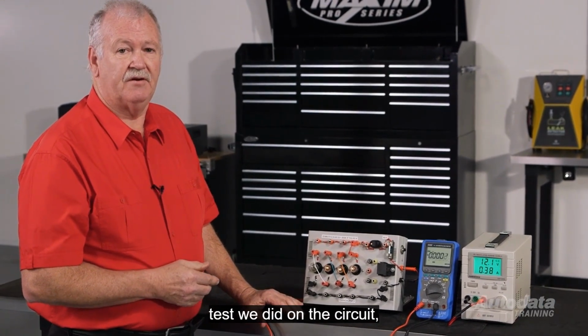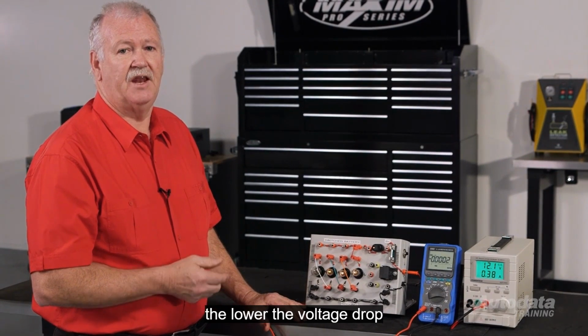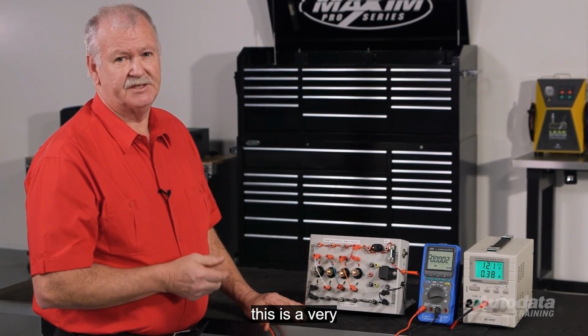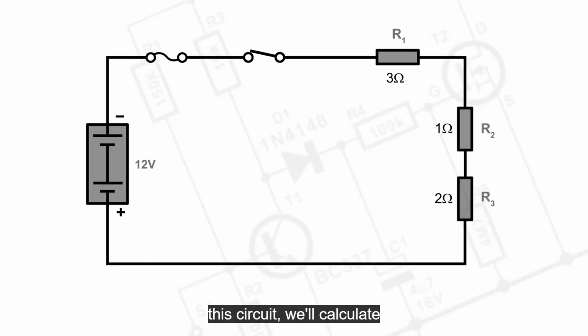From the test we did on the circuit, we saw that the lower the resistance, the lower the voltage drop. This is a very important relationship. Looking at this circuit, we'll calculate the voltage drop across each resistor. To do this, first we have to calculate the current.